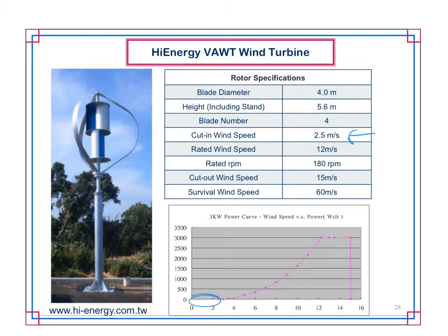So at that point, you would shut it down, because you cannot slow it down enough, so you might let it freely spin. More than likely, you would try to put a brake on it and lock it in position, because if it's spinning, you just can't control it. So you might as well slow it down and stop it in position. Again, this has to be sustained wind speed, so if you have a gust, there's not enough momentum. It takes enough time for momentum to build up to get these things to accelerate. These are massive systems with high levels of inertia, so you need a lot of energy to get them to accelerate. But if you have long sustained wind, you could do that.